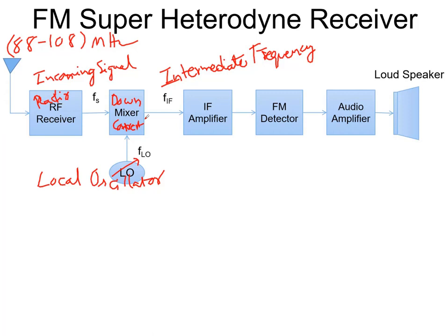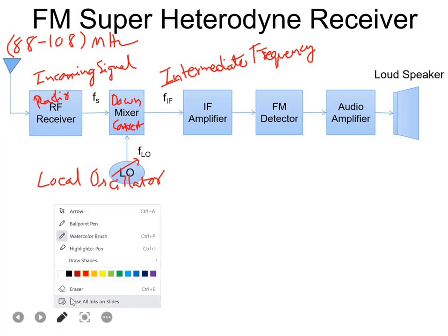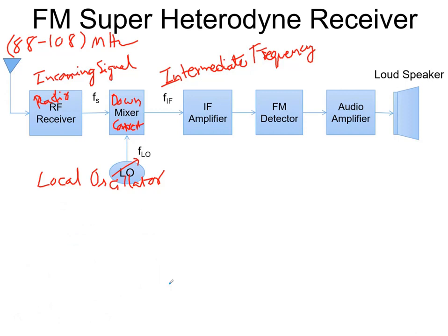And here the basic relationships you can take as notes are: the intermediate frequency for FM is the difference between the local oscillator frequency and the signal frequency, which may be maintained, unless given otherwise in the problem, at roughly around 10.8 megahertz.